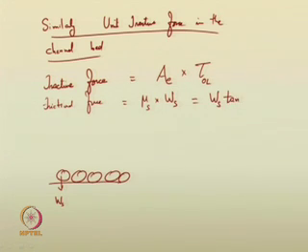We have already found that for any given material mu s can be described through the angle of repose. So, W s tan theta r. Therefore, the tractive force can be equated with the frictional force.